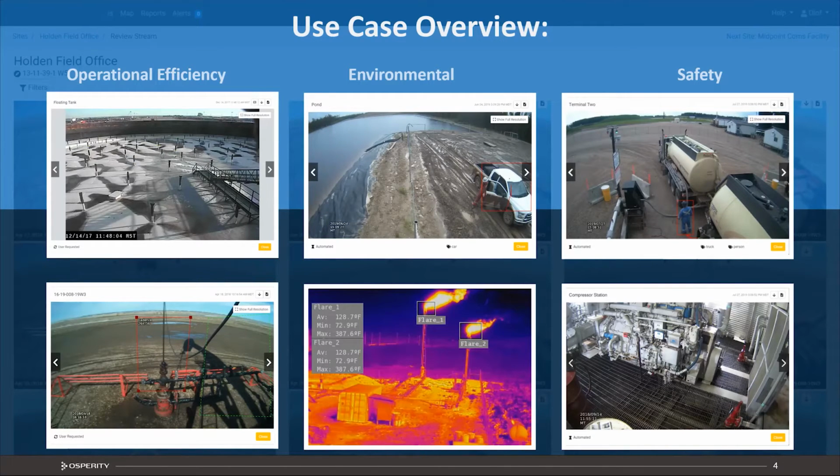Now, a lot of people say, well, wouldn't there be a sensor on that floating roof? There is, but it's on the inside at the bottom. It's not measuring the depth of the snowpack on top, which is necessary for both weight and safety, because if the snow is higher than the top of the tank, obviously it's going to come over the edges.